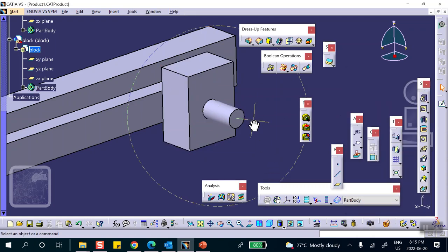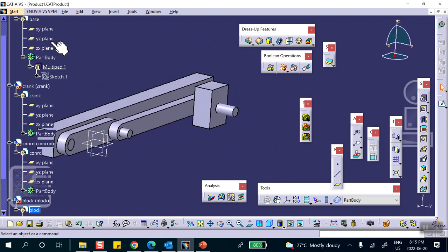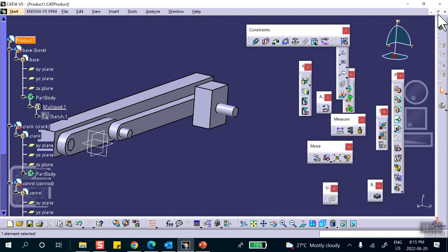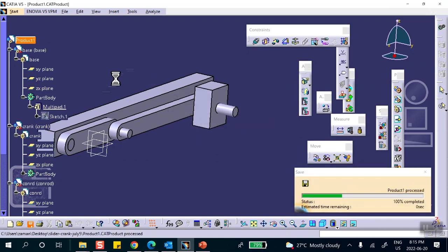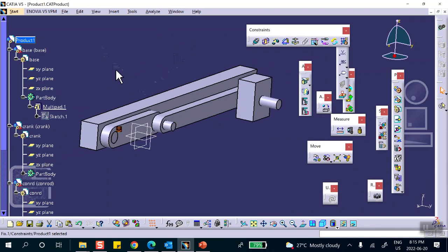And there we are. Okay. Very good. So let's go all the way to the top. Double click, save this thing. And now we're going to do assembly design to make it look the way we want it. First of all, let's anchor the base, because I'm going to be using the magic wand to automatically create the joint.